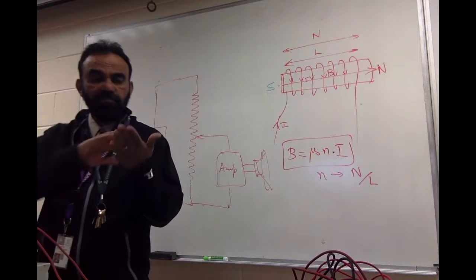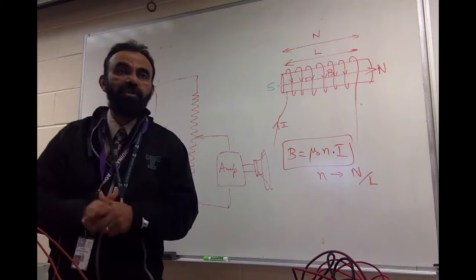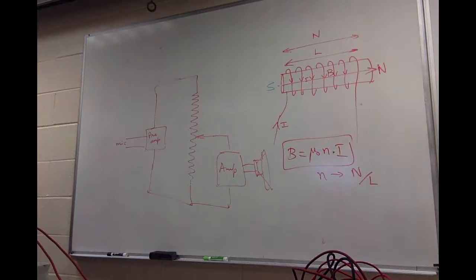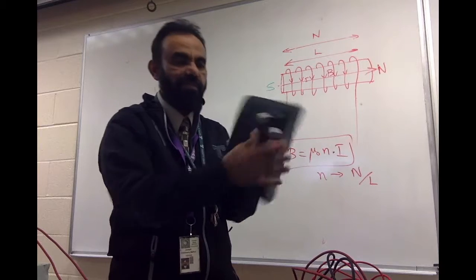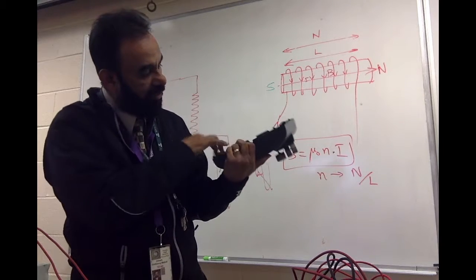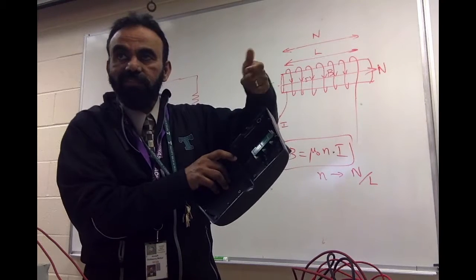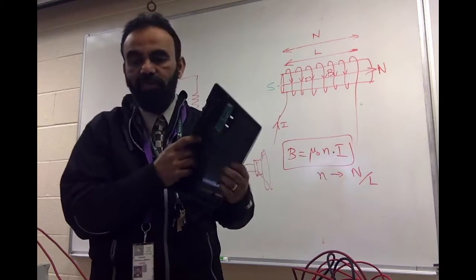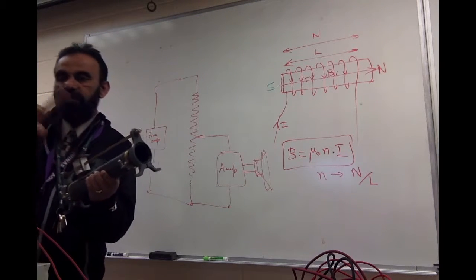You can have a carbon ribbon and get the same potentiometer action. This is just a part of the yoke. You see this? Throttle, mixture, props. What is inside here? Potentiometers. You can see 3 mounted potentiometers with 3 terminals. So when you're doing that, you are rotating it. And when you rotate, instead of you sliding it like this, it's basically doing a rotational thing.